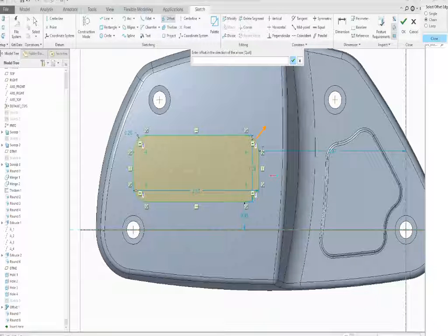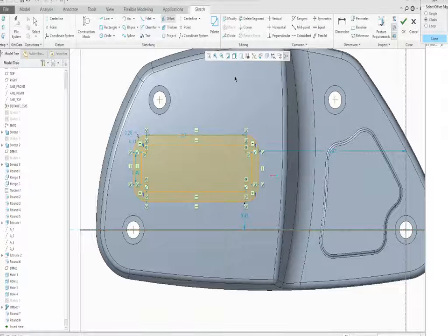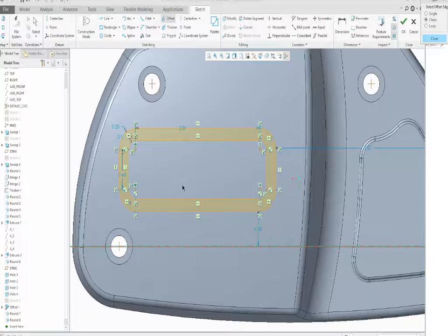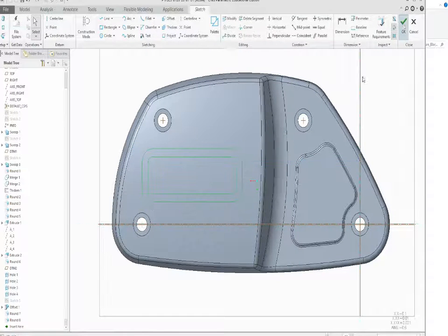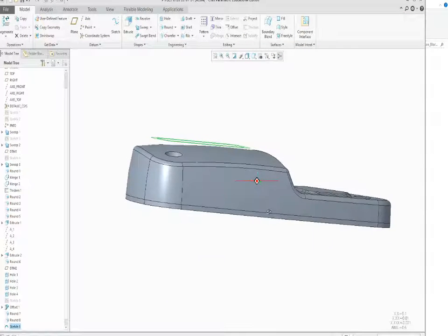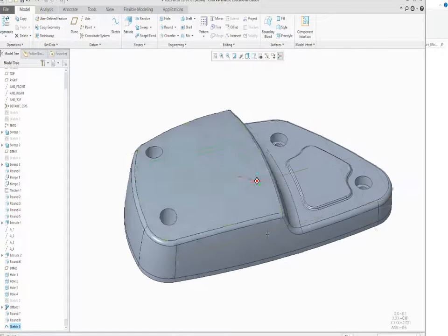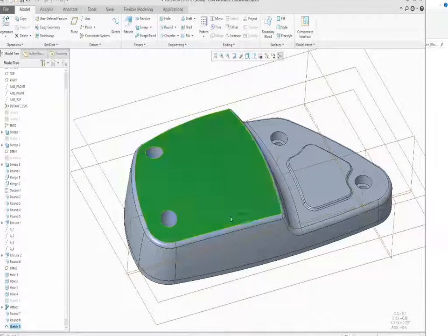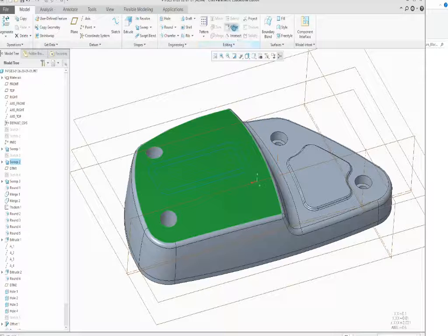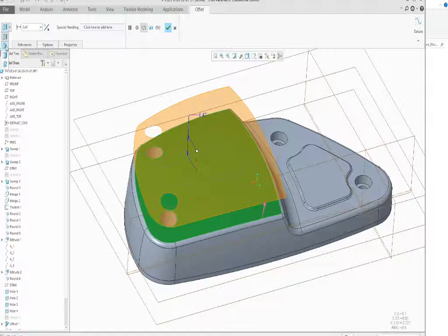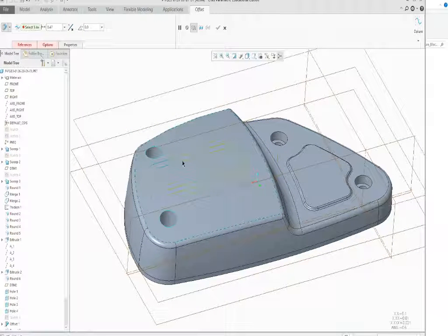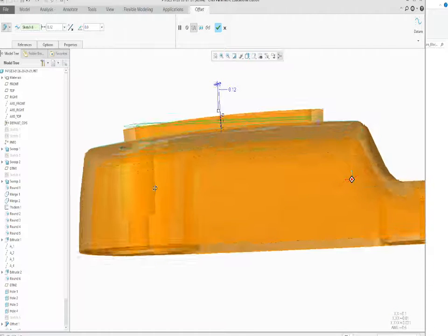It's going to tell us the negative, so we want to go the opposite direction, and we want to do about 100 thou, 150 thou, so I'm going to go for a negative 0.15. And now I've got that profile for the raised surface. I'm going to say closed, say OK. Once you have that, it's got to be above the surface, be careful, and then I've got to touch this, say offset. Move it to tapered, select the sketch, and there's our little raised surface on there.